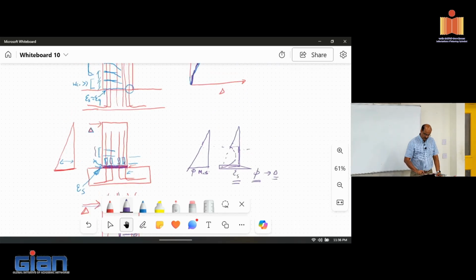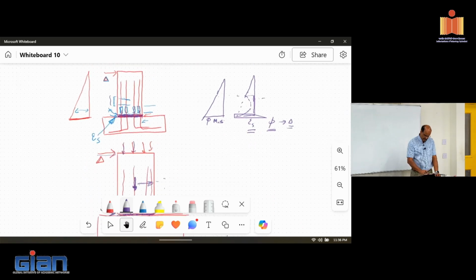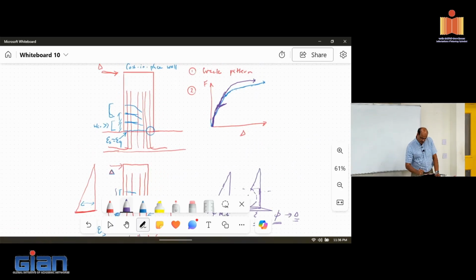So you may develop some response initially. The crack opens up. There will actually be some other form of inelasticity kicking in, or reduction in strength kicking in. That's because initially your neutral axis depth is the entire length. After you open the crack, your neutral axis depth gets smaller and smaller as it starts to rock towards one side. And as you continue to increase the displacement, at some point it's just going to come down and completely fail, or you just lost the wall.